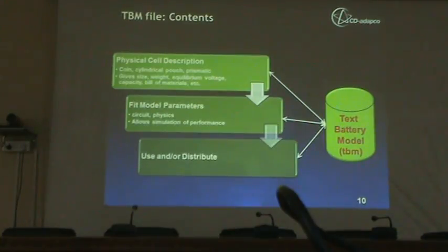Once you provide this, you can run a 1D simulation in Battery Design Studio. It will give you all the electrochemistry properties along with a lump parameter for temperature. It will not give you a distribution of temperature along the cell, but only an average or lump value of temperature. So a preliminary thermal analysis can be performed.